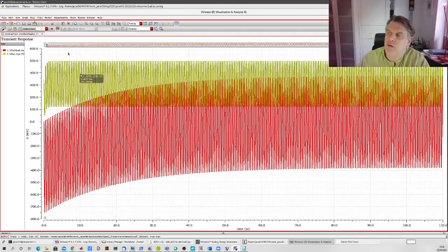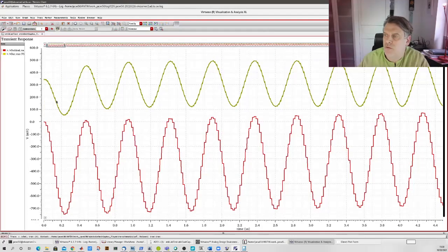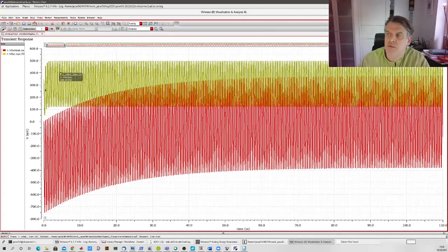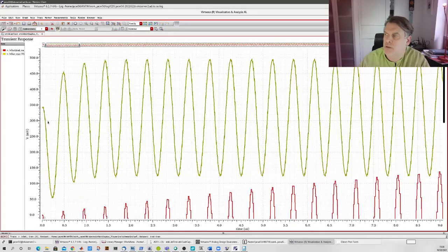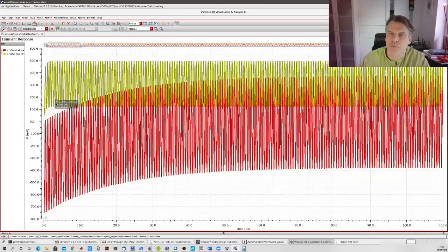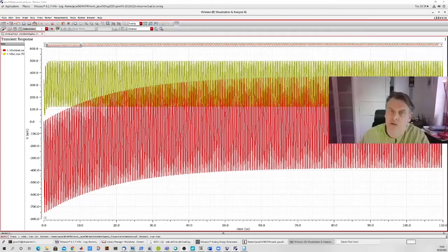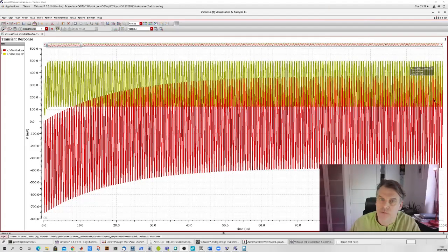The red one is the ideal one. The yellow one is the non-ideal one. First of all, you have a slight settling behavior going on in the beginning. You have to charge internal nodes and voltages to turn the machinery on. You have to remember that when you run your simulations to find, for example, some amplitude levels. Typically, it's better to look at the end of the graph instead, if you look at, for example, min versus max to find an amplitude.